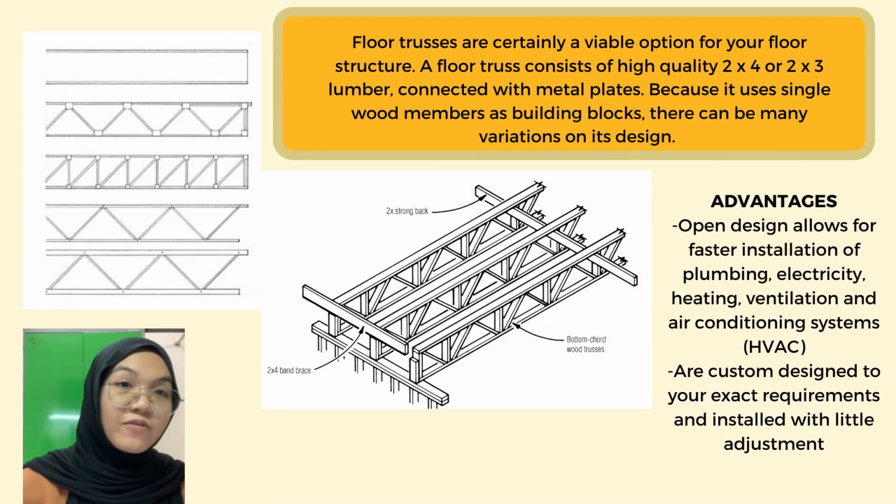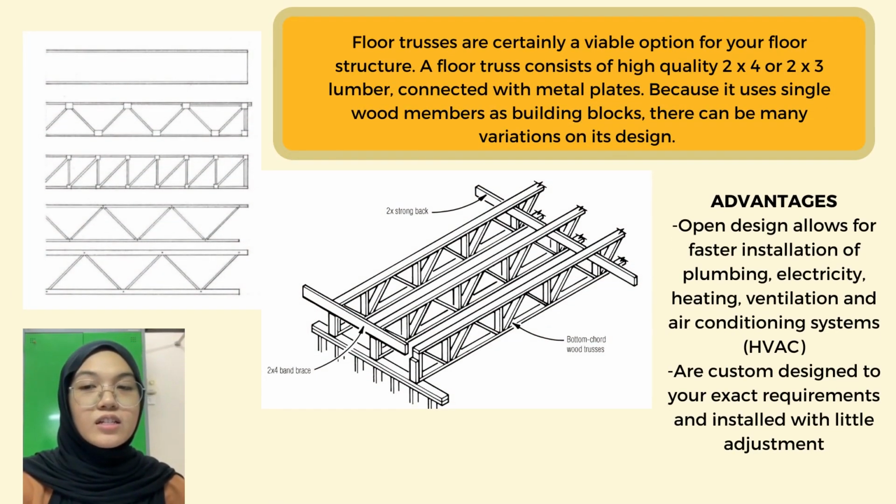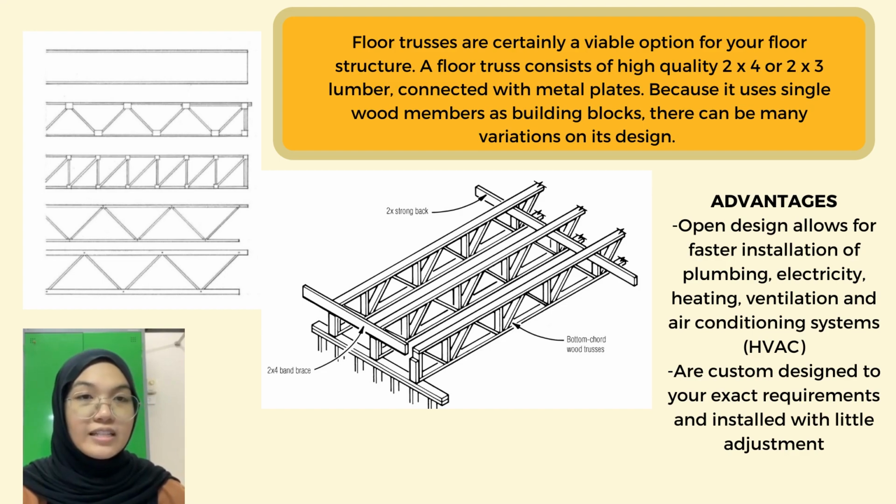And next one is floor trusses. They are certainly a viable option for your floor structure. Floor trusses consist of high quality 2x4 or 2x3 lumber connected with metal plates. And because it's a single-use wood member as a building block, they can come in many variations of designs.